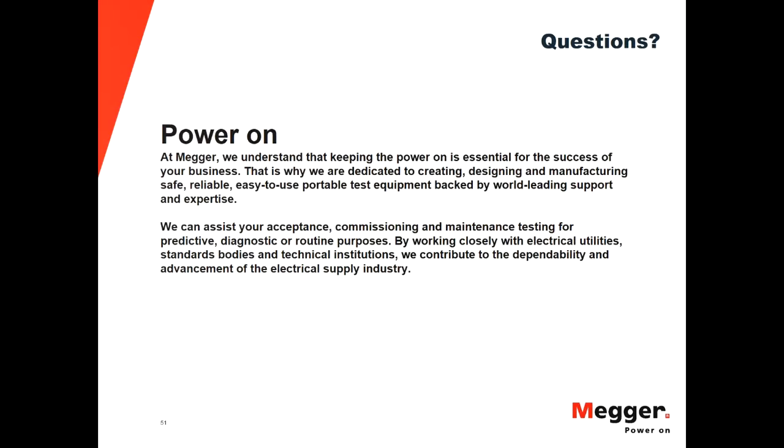So as a person that is going to review the result or a test report that was not present at the moment of the test, you want to know what the condition of the charger is, and what the condition of the cells is prior to starting the test, and that's what these two measurements will give you. So you have very good criteria when reviewing the result and when reviewing the report.